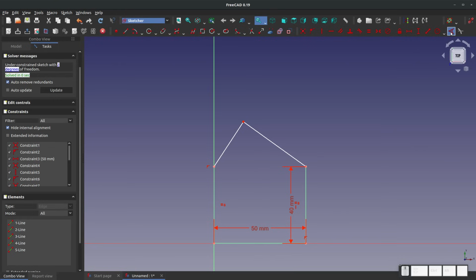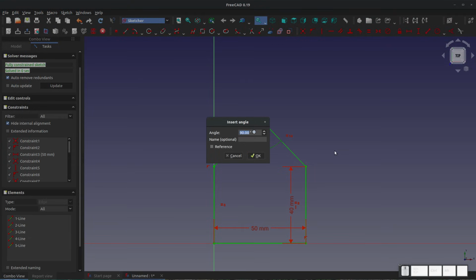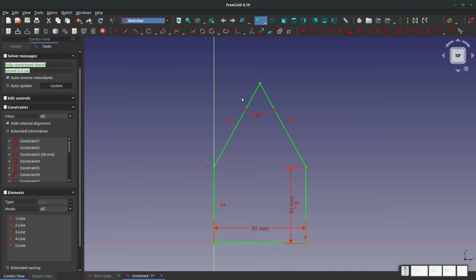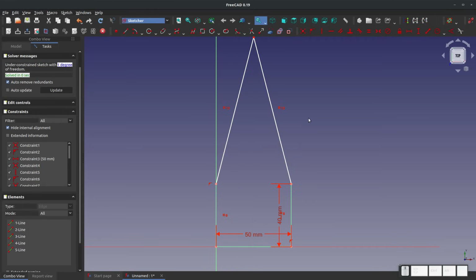Well, I can choose an angle tool, right? So I select this button, fix the angle of a line or angle between two lines. I click on the two lines, and I can make that 90 degrees. And now it's held to be 90 degrees, and I can use the same equal as before. So you can use perpendicular, or you can use angle and select 90 degrees, and it works out the same way. Likewise, I can choose a 60-degree angle, and that will give me a roof of 60 degrees, or 30, right? Whatever we want. So I'll delete that.